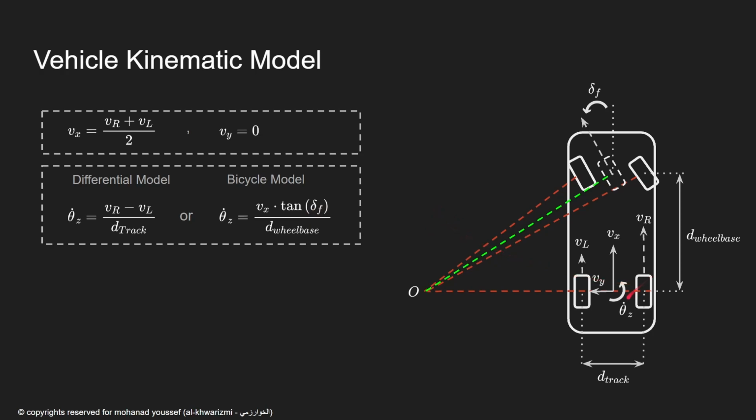The heading rate can also be measured directly from the inertial measurement unit sensor, specifically the gyroscope. But with the gyroscope, it needs more processing, like estimating the sensor offset and doing some calibrations before really trusting it. This calibration can be done during standstill in order to know exactly the offset of the sensor.